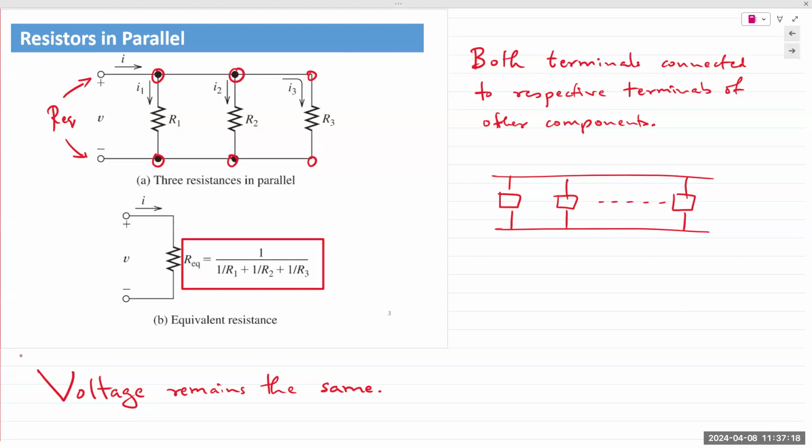Whether you are taking the lab or you are not taking the lab is irrelevant. As a professional engineer, later on in life, maybe a few years later, you might be working with circuits. This is something to keep in mind. If you have a source connected to a circuit and you try to measure the resistance, you will obtain an incorrect value. So you do not want to have a source connected to your circuit while you're measuring resistance.